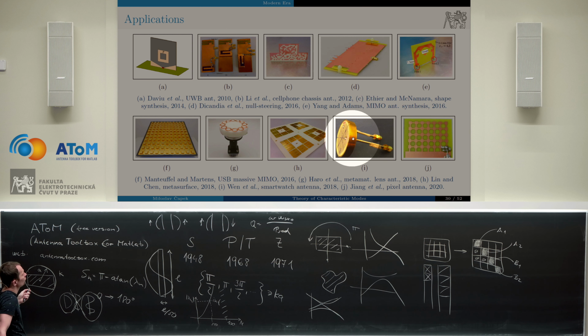And if I decompose these matrices into characteristic modes, and visualize the current densities, like here, I realize a quite shocking fact: for example, the eigenvalue of the first mode is quite comparable. They are almost the same. And by the way, the current densities, visually, are practically the same. But here I decompose a matrix which is 20 times smaller, and consider that there is a cubic algorithmic dependence on how fast the decomposition is. And for the second mode the same is valid, and for the third as well. Just compare these two eigenvalues.